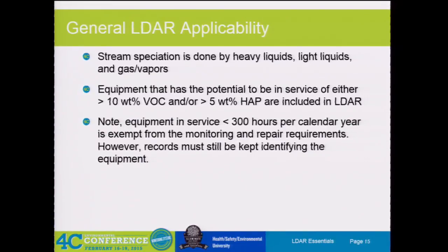It's not just as simple as letting drafting know right now. It depends on how robust you want your program. Most folks with your PSM department have a 5-year requirement to keep everything up to date. So at least every 5 years, you're going to get a new set of drawings. But if you're out in a unit and you find one line that is not on there, I would update it, and then your LDAR contractor or whoever is involved keeps working on that.